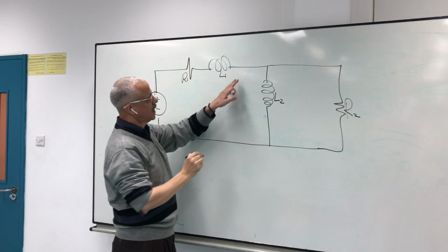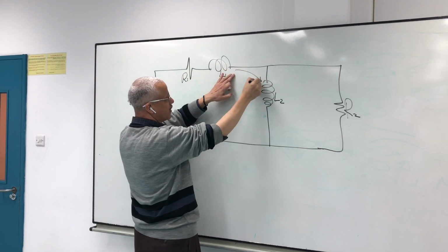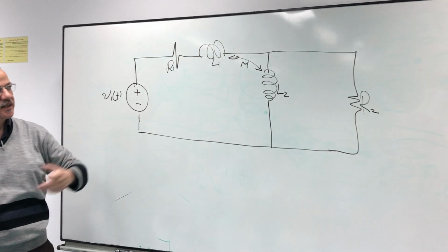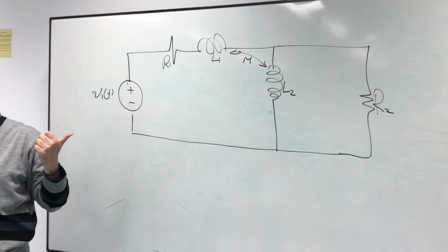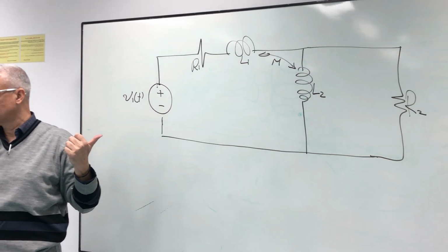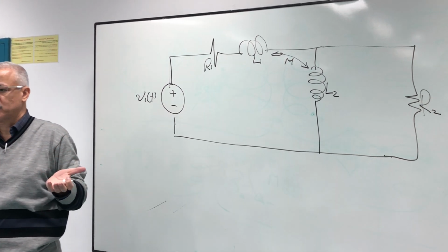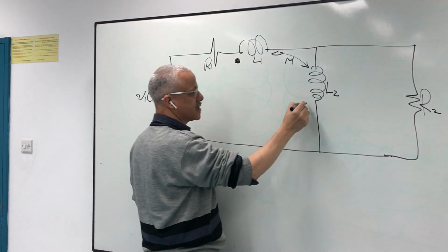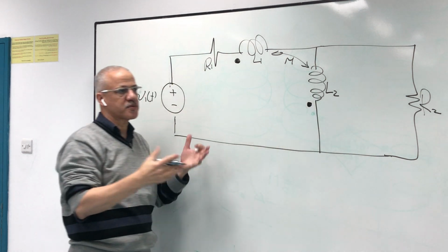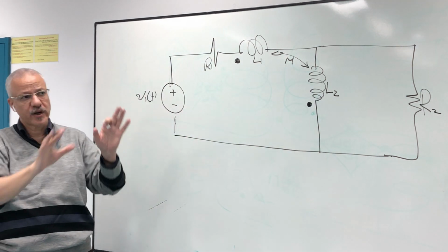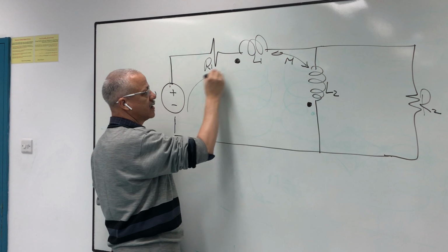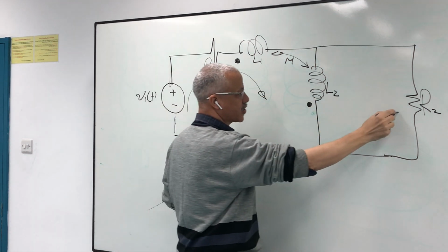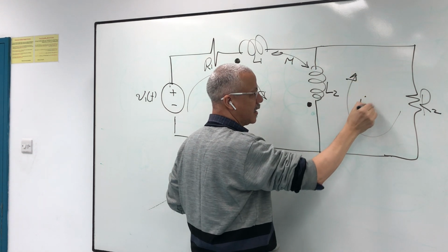It's okay. And there is some kind of mutual inductance in between called M. Something is missing here: the dot. We should determine which dot. So excellent, there is a dot here and a dot here. Assume the currents in any direction and we'll respect it. So here I1, and in the same direction, I2 of t.